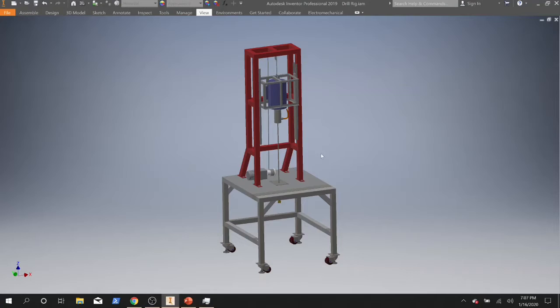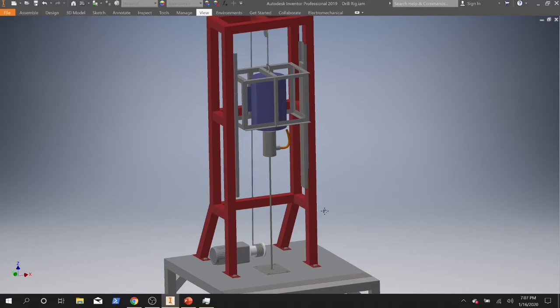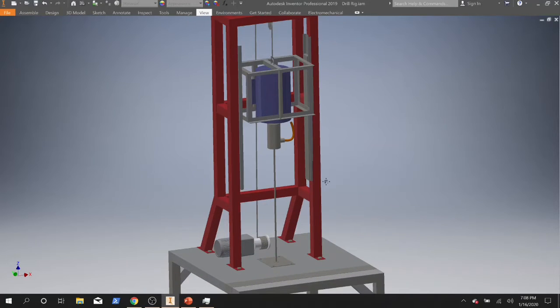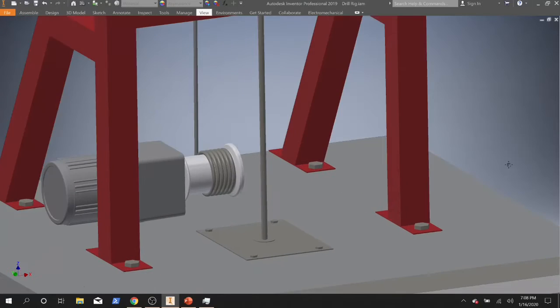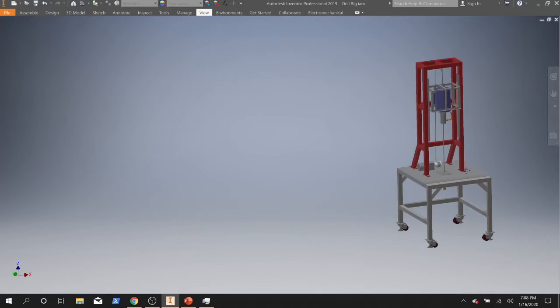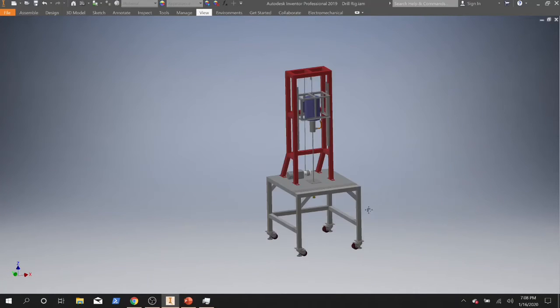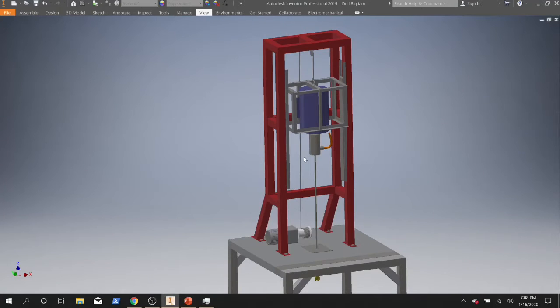The structure consists of a derrick seated atop of the table, all constructed out of 2-inch square steel tubing to provide a strong and steady foundation for the drilling operations. The derrick is bolted on the top of the drill floor and allows for easy disassembly for transportation. The rig provides the structural support for our 3 HP top drive encased within a motor housing.